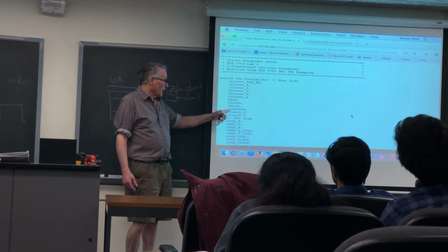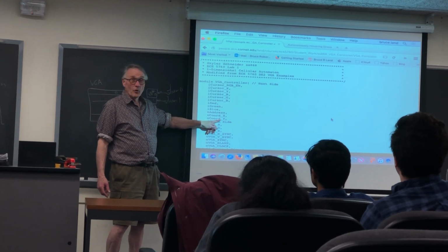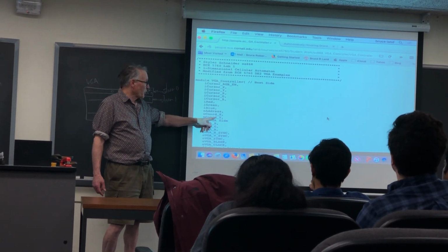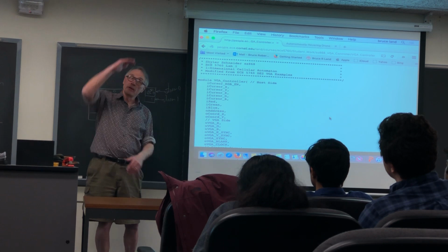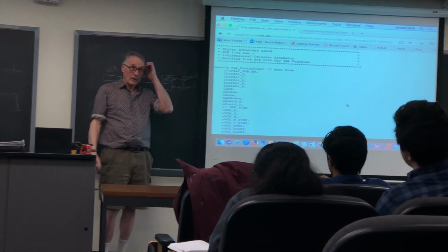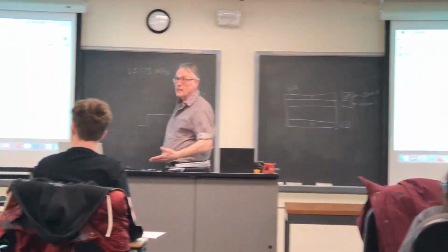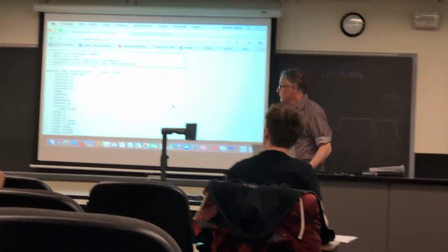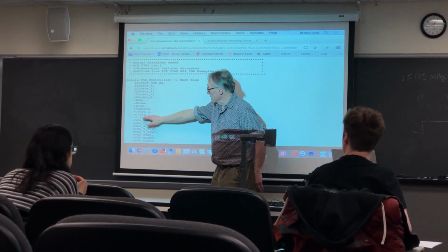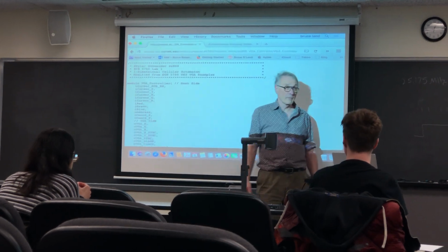Or you say, if coordinate Y is less than 240, make it green, otherwise make it blue, and then you'll have the top half of the screen be green, the bottom half be blue. That's how you test the controller. Once you get the controller running, then you can connect memory to it so that these addresses get color feedback information from memory.